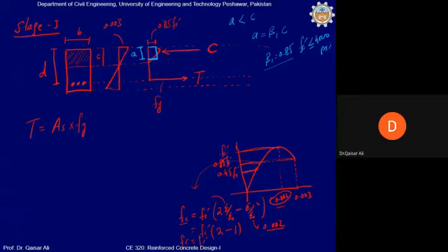Then for each 1000 increment above this value, like for example for 5000 psi, the beta 1 will be reduced by 0.05. For 5000 psi, the value will be 0.8. For 6000 psi, the beta 1 value will be 0.75. And then there is a minimum limit on this, that beta 1 cannot be less than 0.65. However, for beam, beta 1 will be equal to 0.85.